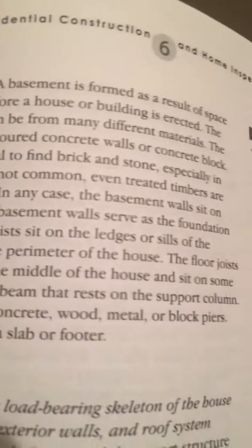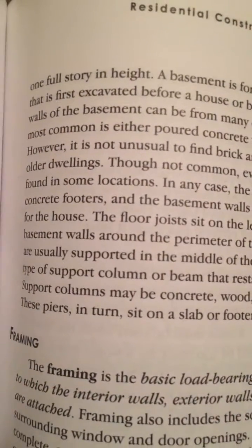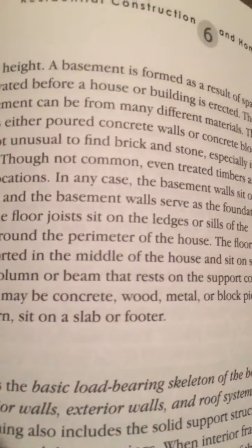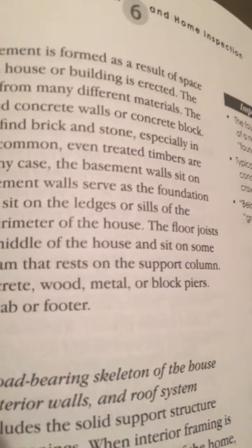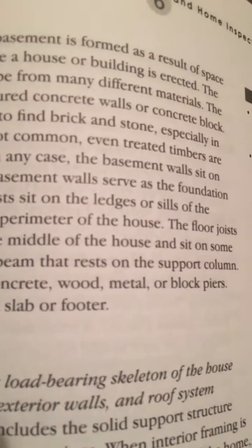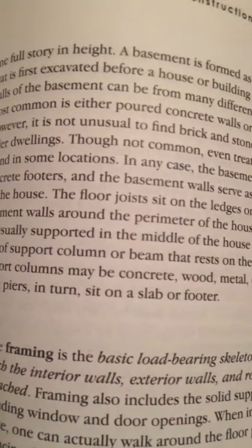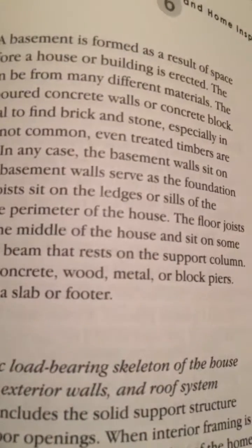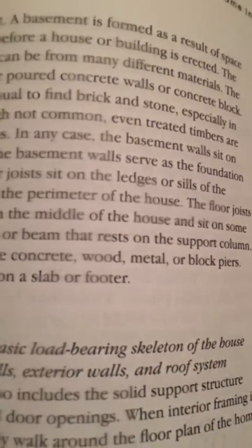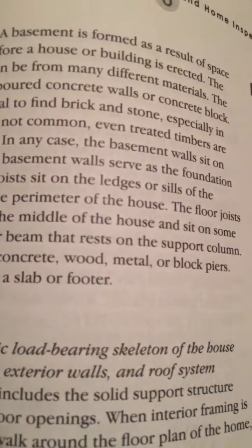Though not common, even treated timbers are found in some locations. In any case, the basement walls sit on concrete footers, and the basement walls serve as the foundation for the house. The floor joists sit on the ledges or sills of the basement walls around the perimeter of the house.